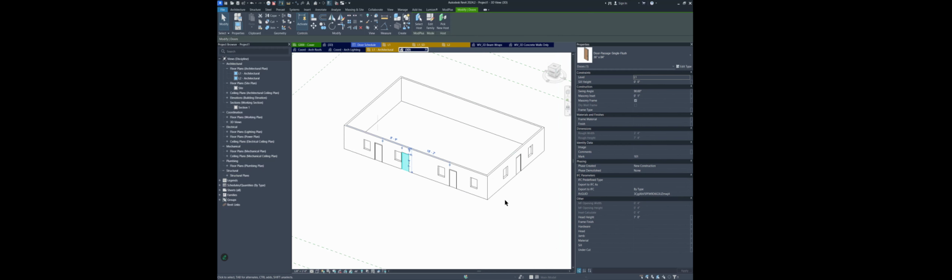There are some things, though. Firstly, I wouldn't go to edit type. You have the right concept, right? Because if I go to edit type and name this description special and choose OK, when I go to every other door here, the description is going to be the same, special, because the doors are the same. I could duplicate the door and create a new type. That's one option, probably more complicated.